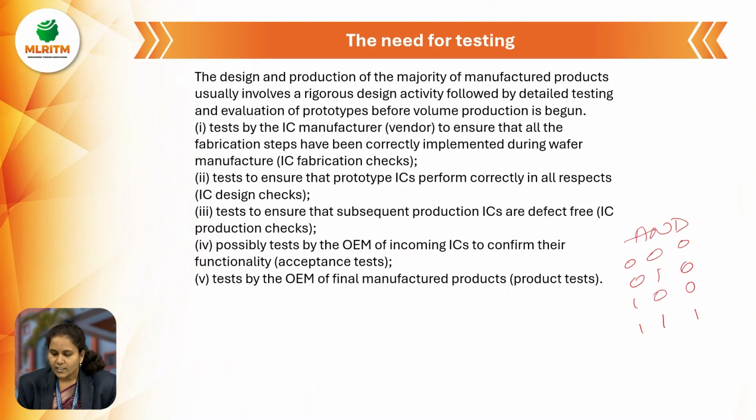For a two-input AND gate, we are getting four combinations of inputs. In this test and testability circuit, we generate these input combinations, check the outputs based on the given inputs, and then identify whether the circuit is a faulted circuit or not.